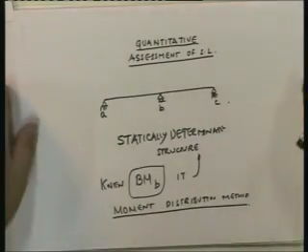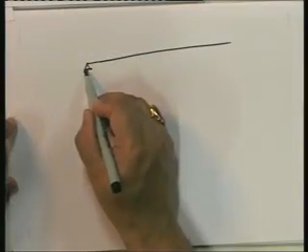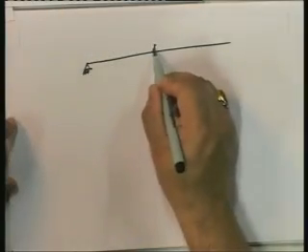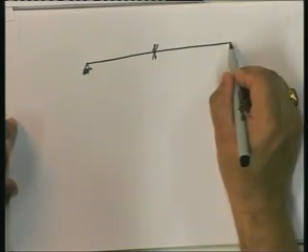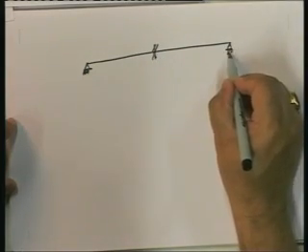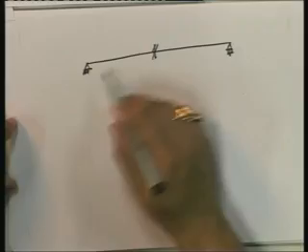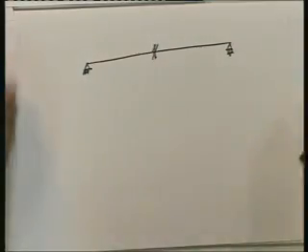Now how do we use the moment distribution method? Well, let's see. What we do over here is actually, in the moment distribution, you actually fix this, don't you? Now these you don't fix because these are ends. Remember, we can do the modified 3 by 4 I upon L and use the modified member, if you remember.